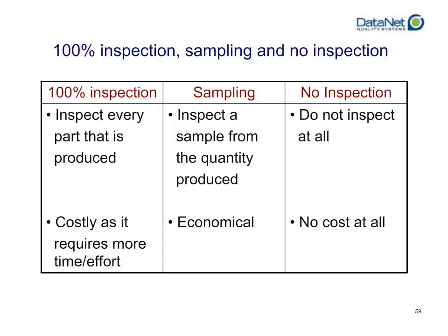On the one hand, it's nowhere near as expensive as 100% inspection up front, and it's nowhere near as expensive as no inspection at all down the road. You inspect a representative sample, a rational subgrouping, a rate of your quantity produced, and it actually in some ways gives you better visibility than trying to record everything at all.